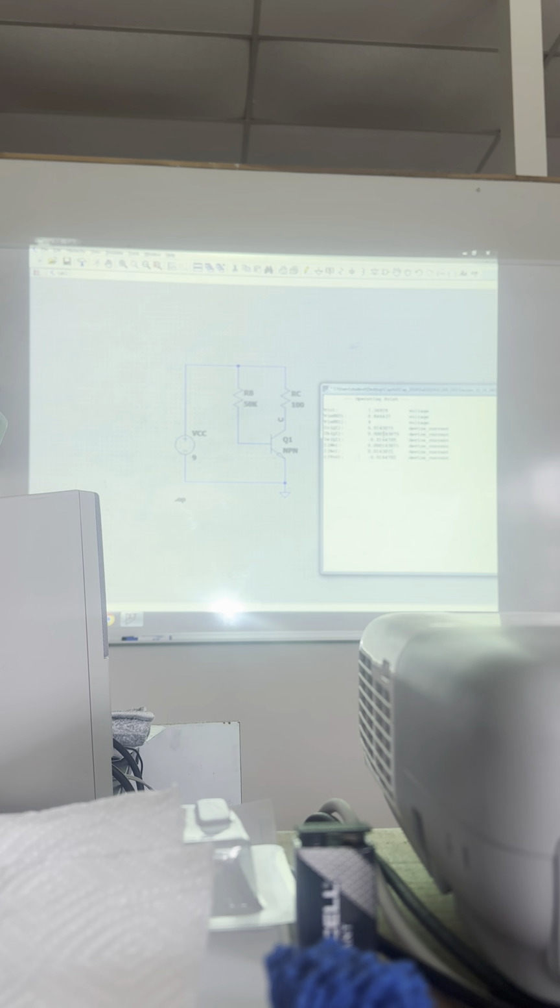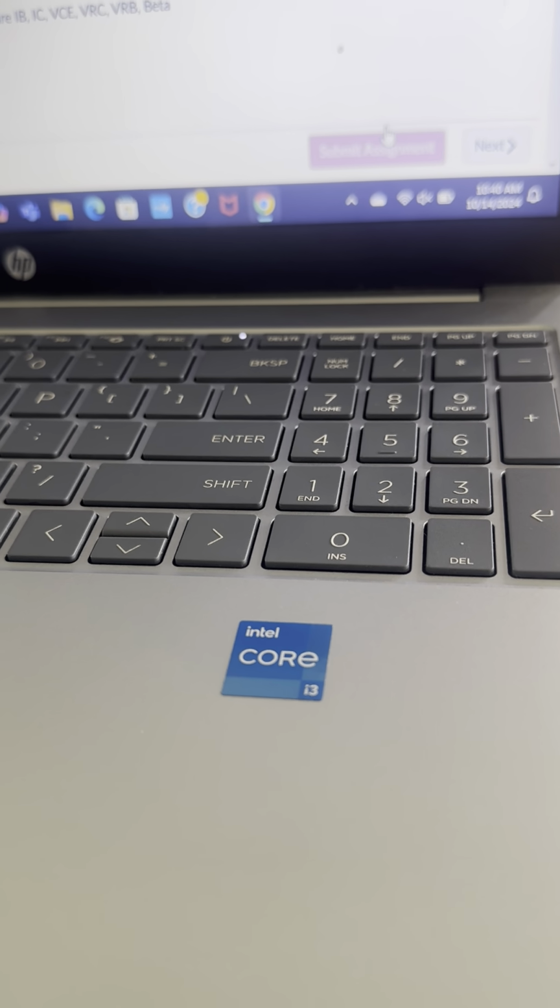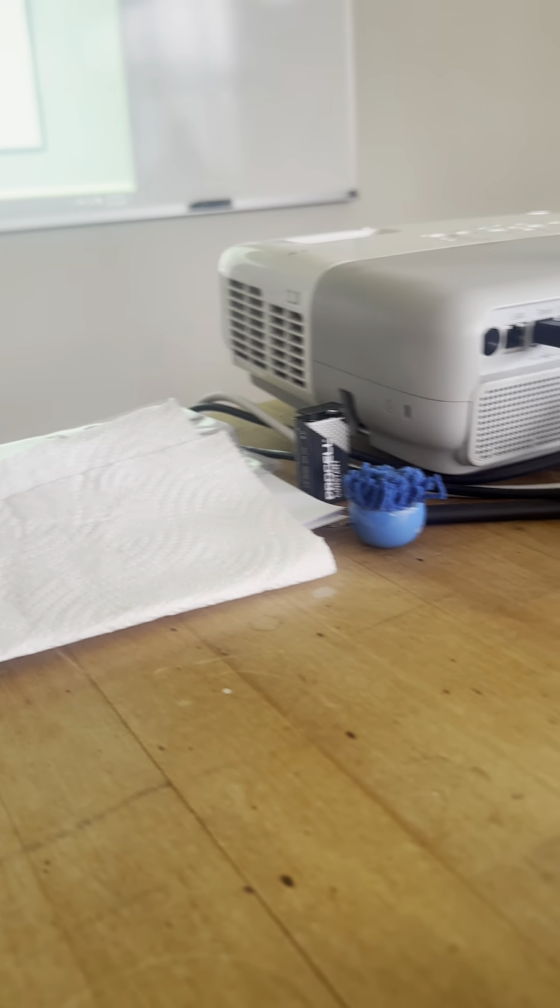16 divided by 0.16. There's 100? Yeah, that's because you didn't set the transistor, so it just uses a default. This is not our transistor. Remember, very good, because it depends on beta. Does that make sense? So we're going to go over here and change this to our transistor, 3904. Okay, run it again.